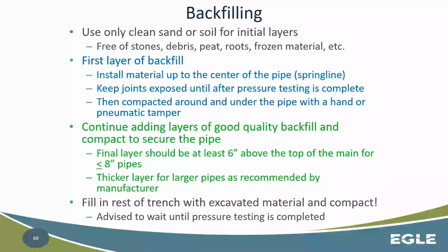Okay, so backfilling, again, making sure that you have a good base to start, you have that water main lined up, everything like that. Use only clean sand or soil for the initial layers. Make sure that it's free of stone, debris, peat, roots, frozen materials, etc. You want to have a good base so that water main isn't flexing and moving all that much, right? Having a really solid base, it's not getting damaged by crushing pressures or something like that.